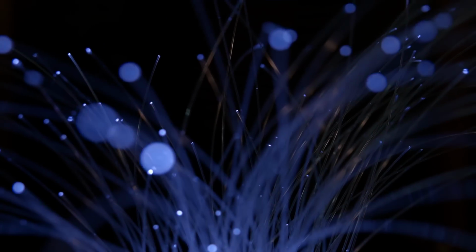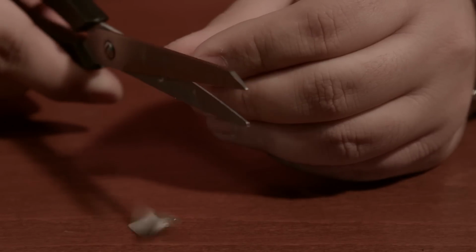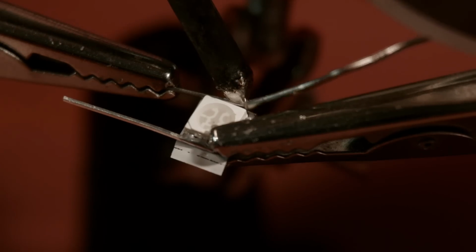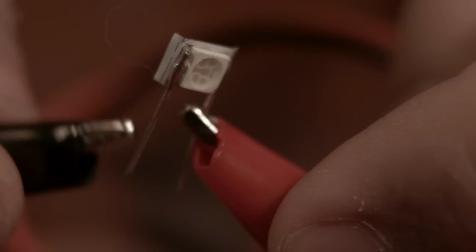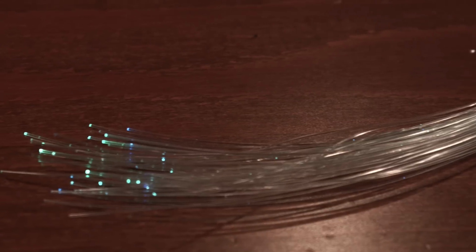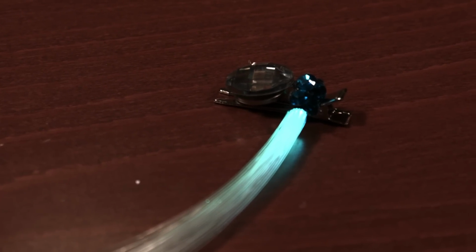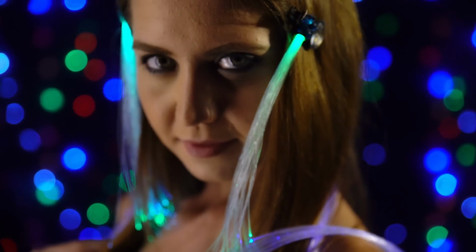Then I got a little crazy and peeled off the waterproof coating and cut out the LED from the 50/50 strip and soldered 2 poles to each side of the LED. The blue and the green will light up just fine at 3 volts. I hot glued the LED to a bunch of fiber optic wire, wrapped it up in heat shrink, although electric tape works too, and attached a 3-volt watch battery and glued everything to a hair clip for this multicolored fiber optic hair clip. But why stop at a hair clip?